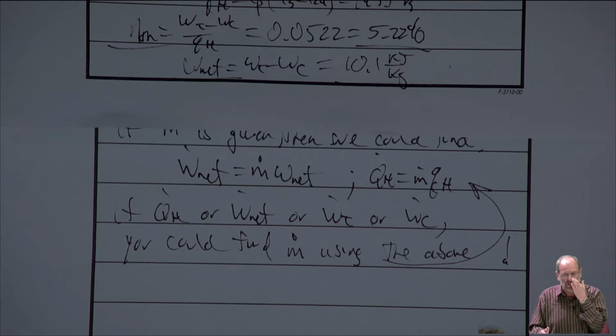Lots of different types of problems, some constant volume problems, some constant pressure problems, like if we have a frictionless vertical piston cylinder device where the piston is free to move and maintain a constant pressure. So a lot of constant pressure problems. We had problems that were called polytropic, where P times V to the nth power is equal to some constant. So we saw how to calculate work specifically for that type of problem.